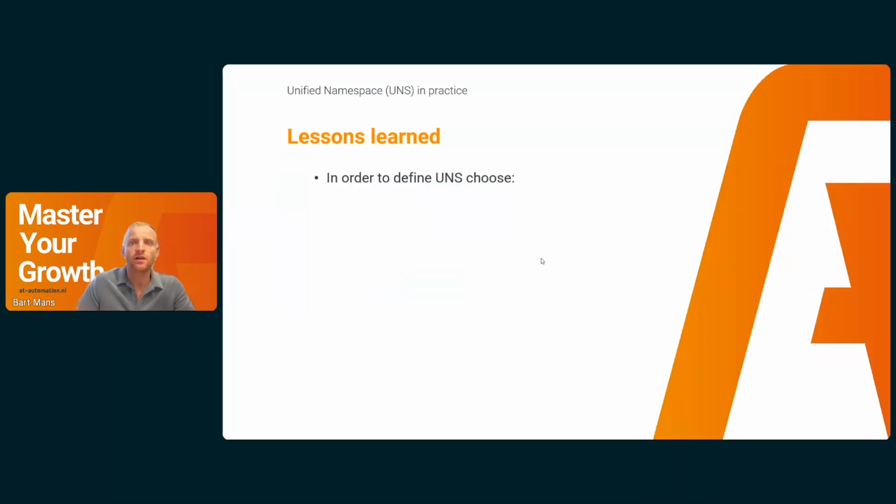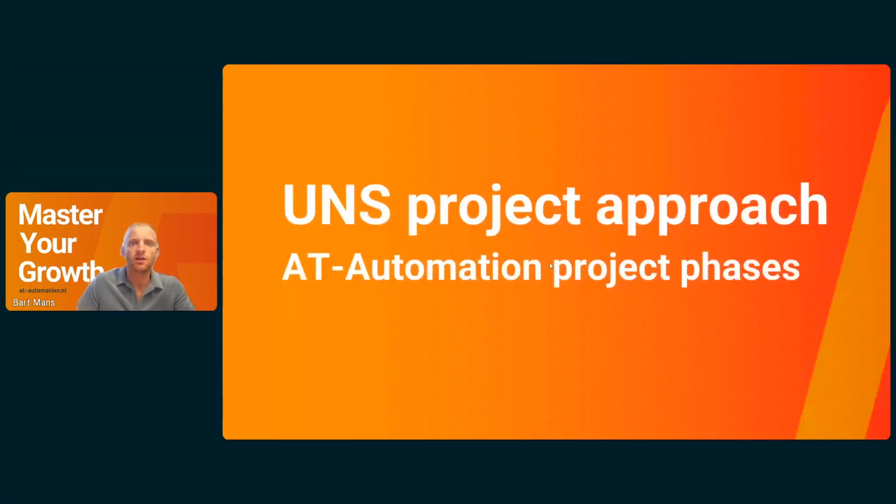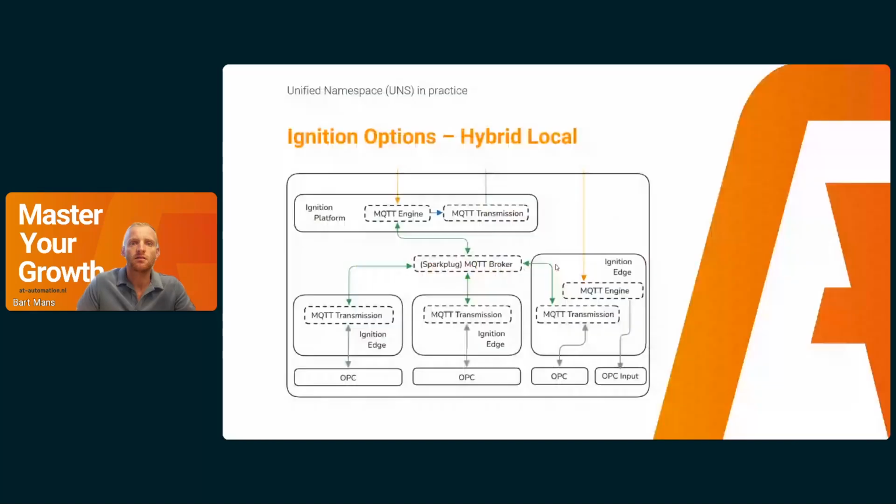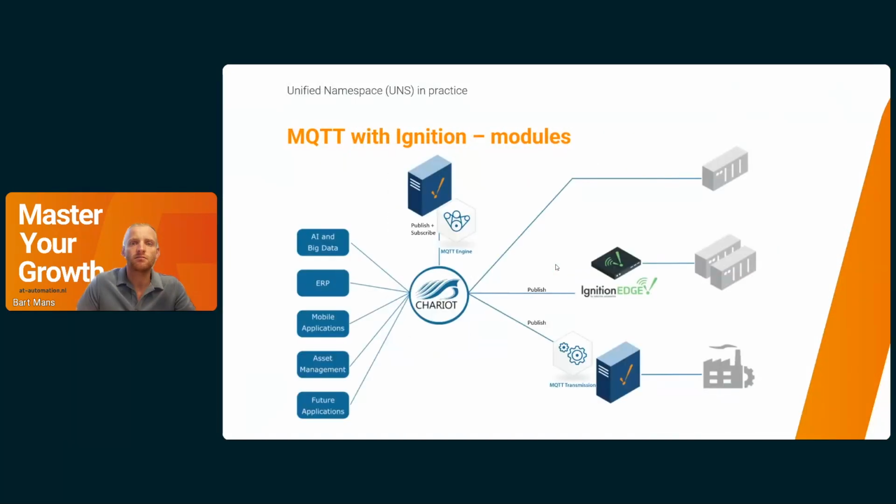So I'll go back a lot of slides actually in order to show that. The architecture. This one. So in here, you can see where the data is coming from. In this case, for this PLC to communicate with this MQTT server, I would need a PLC that can communicate MQTT. It can be Sparkplug B or just a flat MQTT. There are nowadays PLCs that support MQTT straight away.